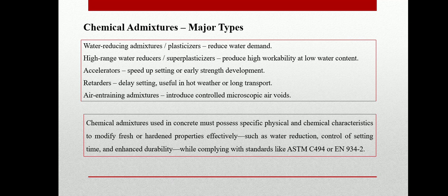Next, accelerators, which speed up the setting time or the early strength gain, useful when you need rapid formwork removal or you are working in cold weather. On the opposite end, retarders delay the setting time, which is particularly useful in hot weather conditions or when concrete needs to be transported over long distances before placing. And finally, air entraining admixtures, which introduce controlled microscopic air voids into the concrete. These are especially important for improving resistance to freeze-thaw cycles.